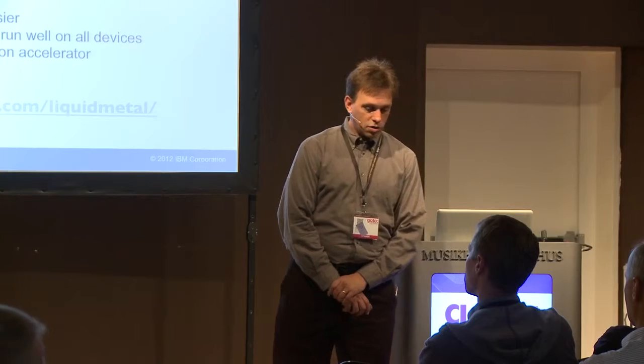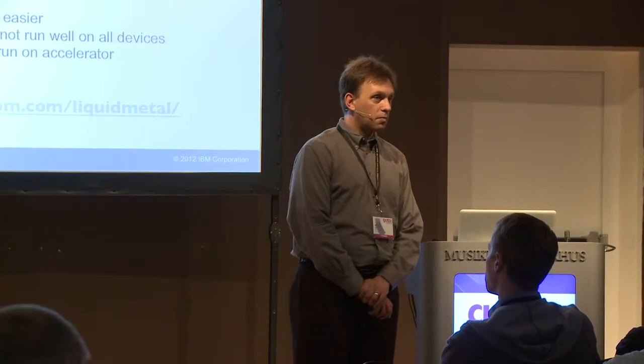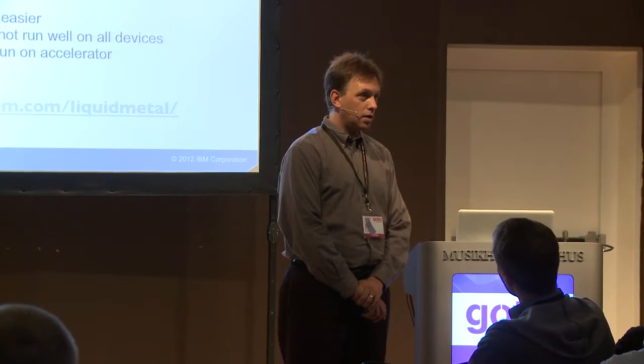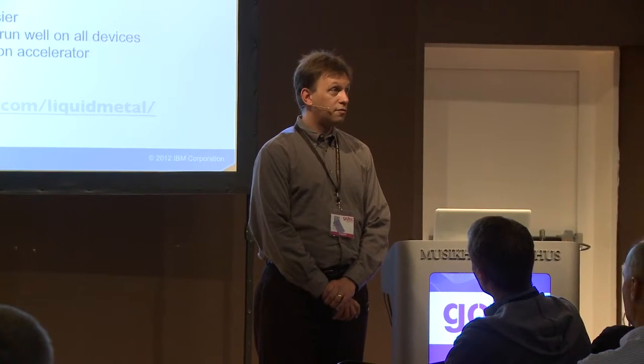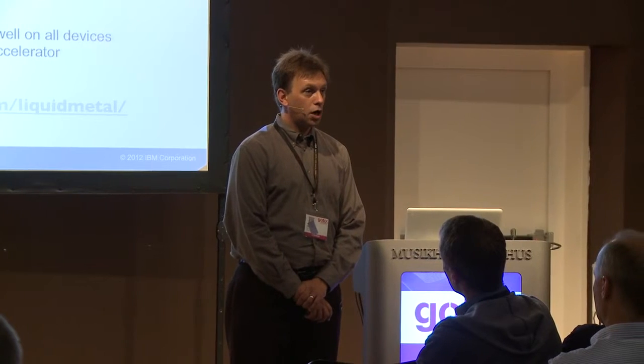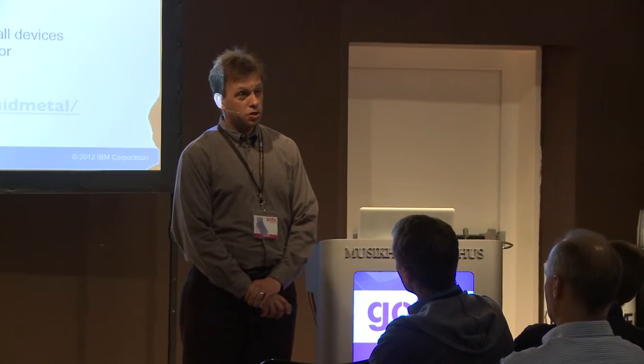So the FPGAs, there's a number of ways to communicate. Right now, yes, our main system is communicating over PCIe. There's also Ethernet as a possibility. We also have, for prototyping, a UART serial connection. So there's many different ways to talk to FPGAs. There are also vendors that do memory bus attached FPGA designs, either with IBM or with Intel. So there's a number of ways, but yes, our primary platform right now is PCIe.